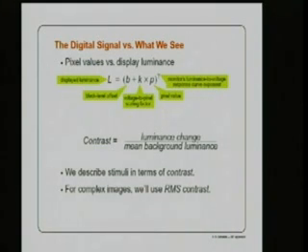What you see is an output luminance on a screen. That luminance is some photons that are coming out from the screen. We measure it in candelas per square meter. And it is related to the 0 to 255 value by this nonlinear function for CRTs. And because I care about what people see, I have to make sure that I'm doing all of my measurements using the displayed luminance.